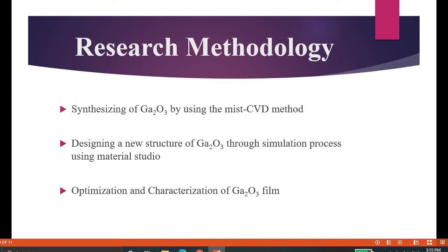Firstly, I would do the structural characterization, which will be carried out on the gallium oxide structure by using FESEM, TEM, AFM, XRD, and also UV-Vis. The purpose is to observe the gallium oxide thin film structure without any significant lattice mismatch between the gallium oxide and sapphire interface. This structural analysis will vary with different parameters.